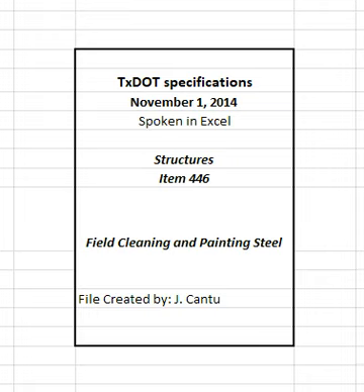4.7.4 Painting. 4.7.4.1 Paint condition. Thoroughly mix and strain paints to be applied. Mix by mechanical methods. Provide continuous mechanical agitation during painting operations to prevent settling. Ensure the paint is a completely homogeneous mixture free of lumps, skins, and agglomerates and contains all pigments, vehicle solids, and thinners required in the original formulation. Keep paint containers tightly covered and protected from weather when not in use.